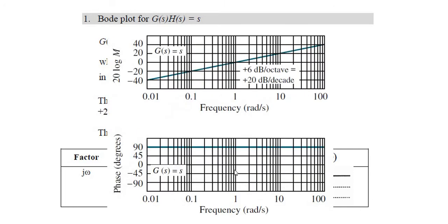If you refer to the semilog paper more clearly, we have 0 here, and the intersection will be at frequency 1. In order to get that 20 dB, you see that at this dB line for magnitude, the scale starts at 0, so we have 20, minus 20 here, 40 up there, and minus 40 down there.